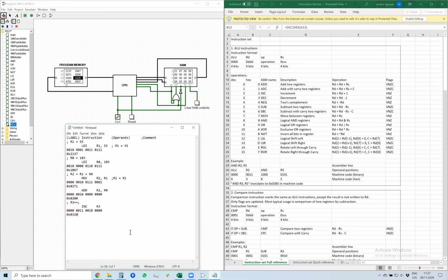So if you wanted to build the most energy efficient processor in the world, then you would want to set the last bits which are not used equal to the last bits in the previous instruction, so that the bits don't change and you don't have to flip some field effect transistors to opposite values, because a processor consumes electricity only on signal changes.